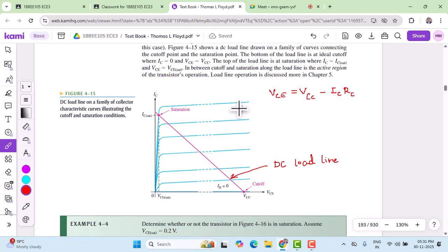We can conclude that for lower and for higher collector current, the beta DC is low, and at some point, say 10 to 15 milliampere, the beta DC is going to be the maximum value. That's how the beta DC varies with the collector current.